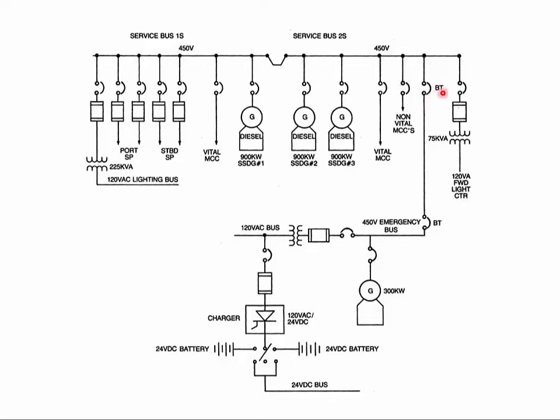And this is a manual breaker. I can open that up. Then I can power up the main switchboard. It will not energize this line, and the transfer will not take place. And then I can get my work done. And when I'm ready and set up to restart the equipment after that temporary blackout, all I have to do is close this engine room bus tie, and then that transfer will take place.